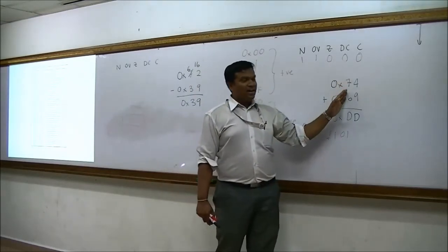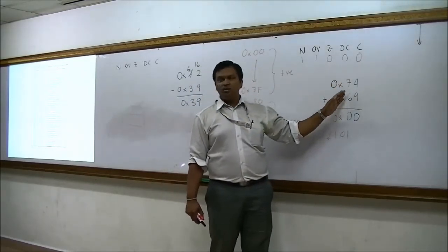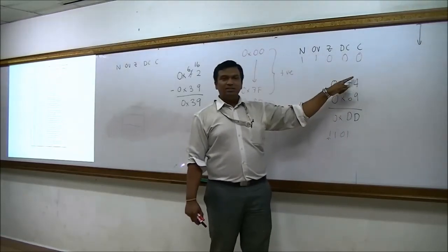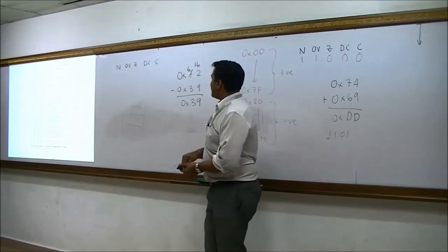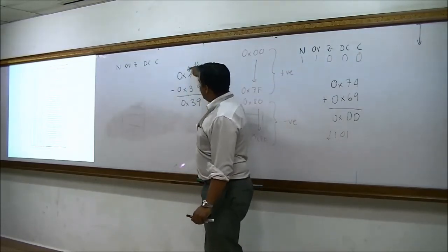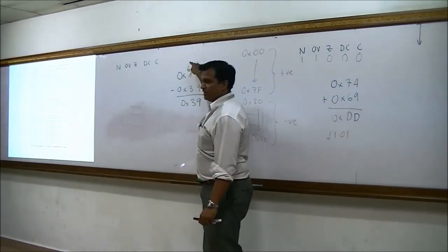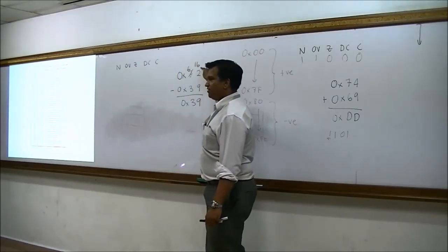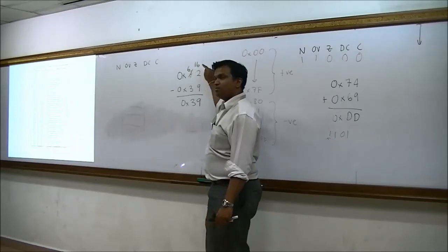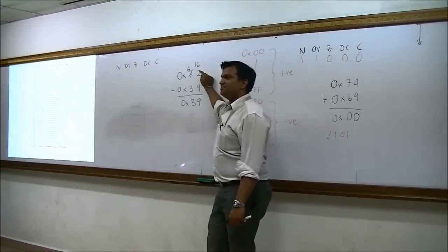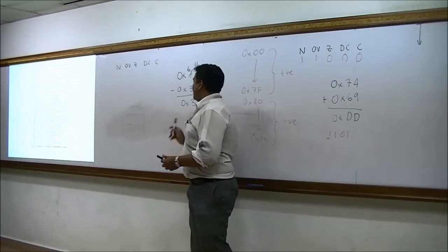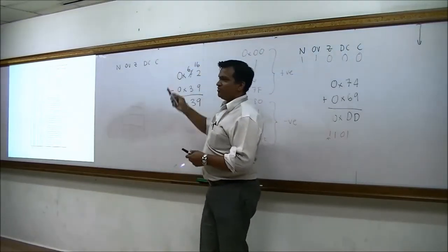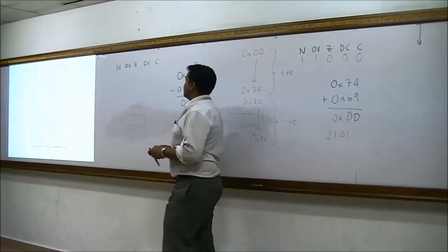And then there is also the higher nibble. When you add, you have a carry, right? That is known as carry. This one is known as digit carry. Likewise, if this number is smaller than this one, it will perform a borrow. That is known as borrow. When this lower nibble doesn't have enough, it performs a borrow. That is known as digit borrow. Can you understand? Yes. So again the question, do we have borrow? No. So what should be the value of C? 0.